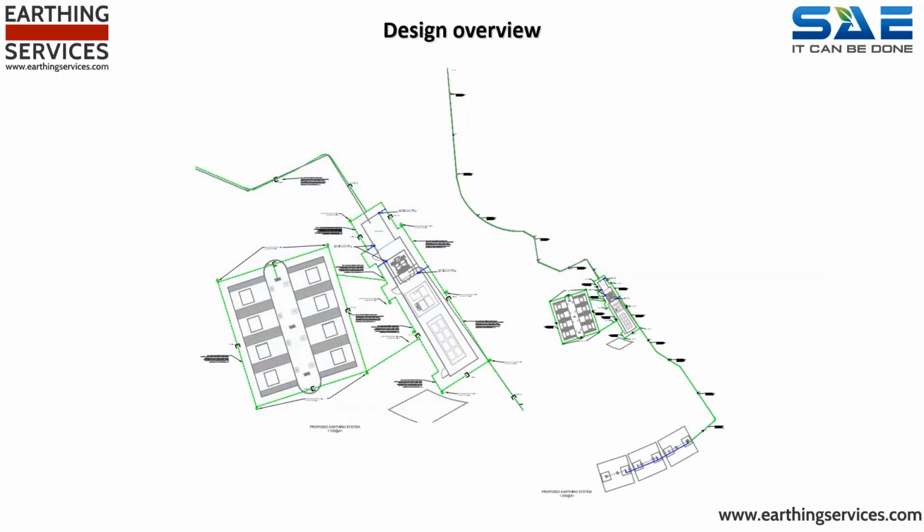The earthing system design had to comply with all relevant standards and project specifications. Due to a combination of a high 1-phase earth fault and a high soil resistivity soil model, an extensive earth is required to ensure the site is classified as a cold site. A cold site relates to a return of earth potential, ROEP, of less than 430 volts. Anything exceeding this would be considered a hot site, which may require additional steps relating to separating HV and LV earthing provisions. The earth system comprised a series of horizontal and vertical electrodes.